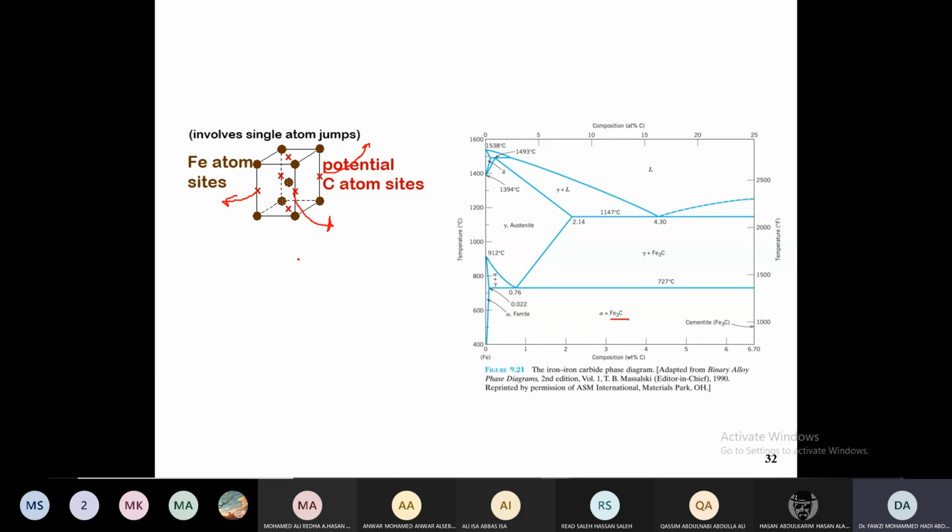We said that you cannot use the martensite in high temperature applications because it is going to change its structure. If it changes the structure, then we have a change in mechanical properties. So basically, we are changing now the crystal structure of the material. We are changing the property of the material. The phase is going to change because of this diffusion. The carbon atoms are trapped there, but they are allowed to escape, and they form the cementite phase in the material.